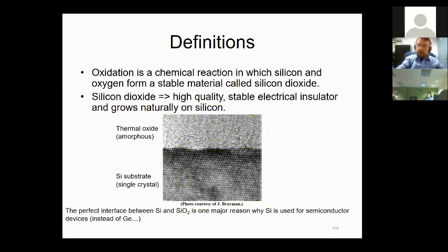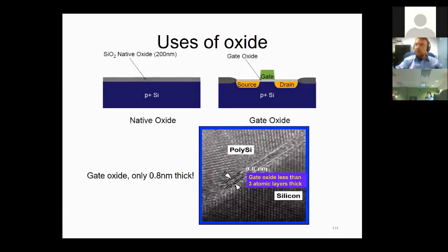All right, so why do we need an oxide layer? Because in the first place, silicon is nice. We can play with its conductivity. That's what I was trying to emphasize over these lectures. As a semiconductor, you can tune its properties by playing with temperature, by playing with dopant levels. All those are fine. You can work around with that. But then when you build your devices, you like to also create an insulating layer too. You like to have some portions that will be isolating the other portions. For that reason, the oxide will be very, very handy.